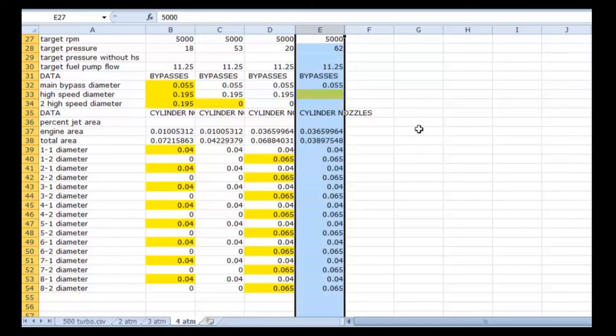In our research, we've worked out a 2-cycle engine combination with 2 stages of supercharging, 1 supercharging and 1 turbocharging with extremely high boosts. And it's conceivable that you can be going to extremely high horsepower levels, approaching 10,000 and even beyond with straight methanol fuel. In addition to this, you can add nitro in ProCalc, and you can start out with small percentages of nitro to combine with turbocharging. And using enrichment, you can accomplish intercooling, fuel intercooling, to keep everything from melting down and continue to be going up in very high power levels.